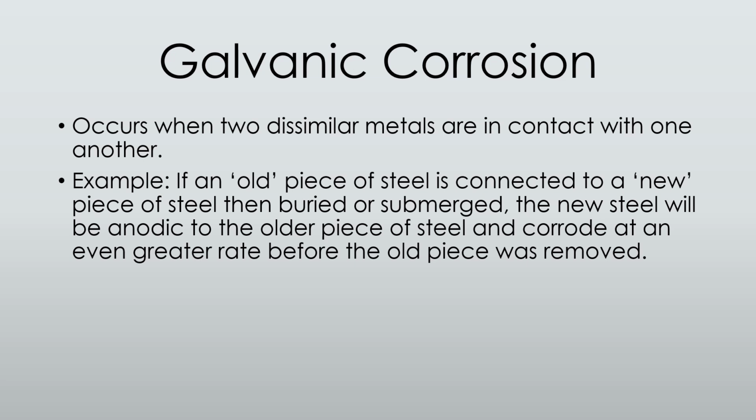Because if we think about the potential difference, those two old pieces of steel that were in place had been in the same piece of ground for the same amount of time, so their voltage levels were relatively similar. But now you've brought in a brand new piece of steel from the factory that has the highest level of potential energy it's ever going to have, next to an older piece of steel that has had time to release some of its energy from its lattice structure.